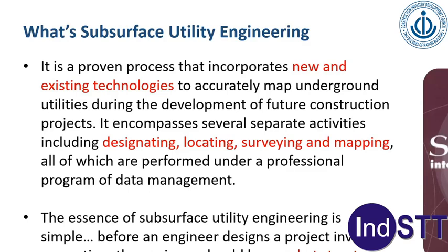Before an engineer designs a project involving excavation, the engineer should know what structures and conditions are beneath the earth and where they are in 3 dimensions. Such structures are usually utilities but may include underground storage tanks, septic fields and other things. That is basically what SUE is. It is use of new and existing technologies to accurately map underground infrastructure before you design or execute a construction project.